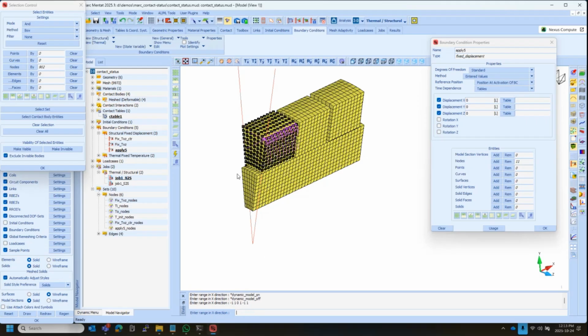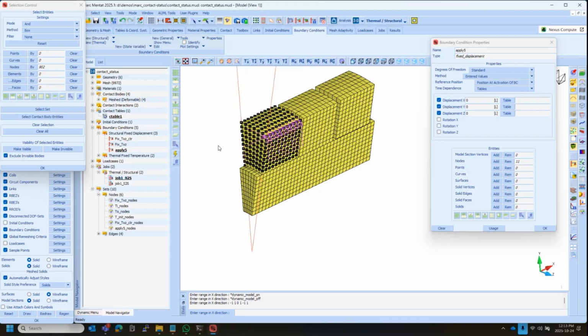Okay. So this is useful in a scripting environment. If I need to, let's say, mesh in Apex or something, and for whatever reason I can't already predefine loads of boundary conditions or some feature there which I'll need on this side, if I know where it is, I can then, using this kind of box selection, automatically select it.